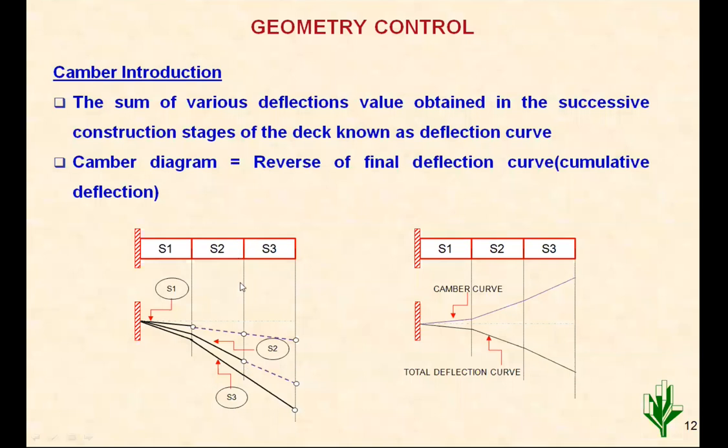Similarly, when S3 is installed, it will go further down, and this is being continued. Now the similar is the other way around also. We will stress the cable from S1, it will go up. S2 will stress the cable, it will go slightly up. So theoretically we can decide, to achieve the aim of say 0, 0, how much pre-camber we have to make.